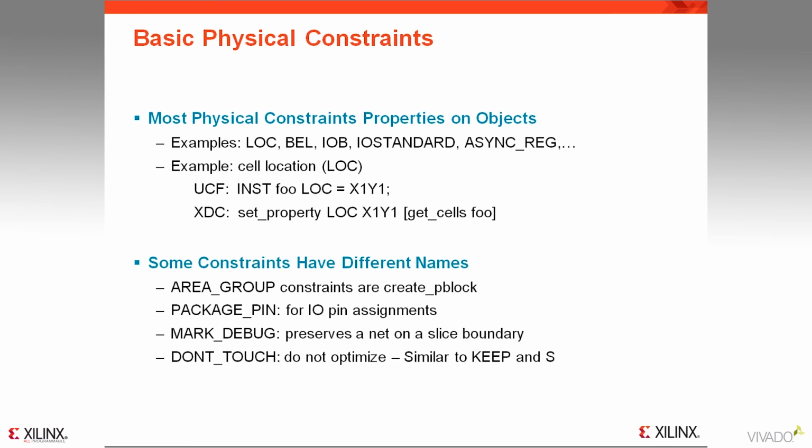There are physical constraints that change names, mostly because the behavior is slightly different. Area group constraints are referred to as P-block or physical block, which was a long-standing PlanAhead floor planning feature. Package pin constraints are the XDC equivalent of a lock on a device pin. Mark debug constraints was added for ChipScope probing to preserve nets for the analyzer. Don't touch constraints preserve nets, pins, and cells and prevent optimization. There are others. These are some of the more commonly used ones.